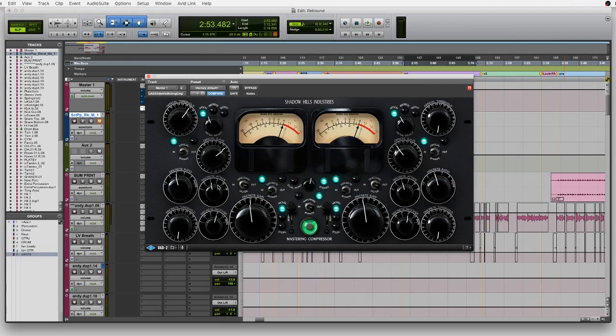The second stage is a discrete compressor with controls for ratio, threshold, attack, and release settings. Select the meters to read this stage. Set your ratio, attack, and release to achieve your desired attenuation envelope, then lower the threshold until you begin to see attenuation. Then adjust the makeup gain accordingly. This section can be bypassed using the bypass switch.